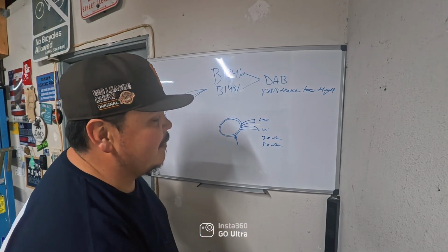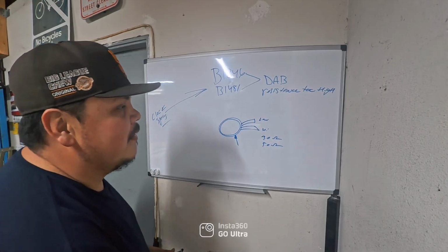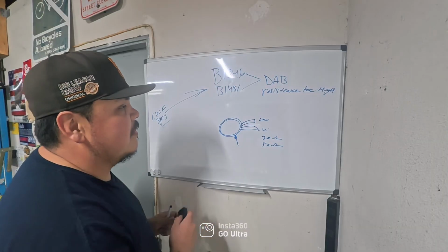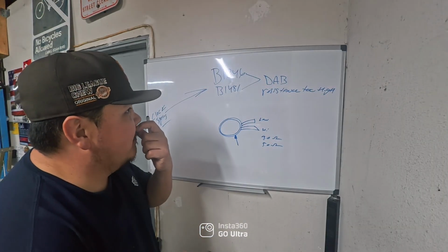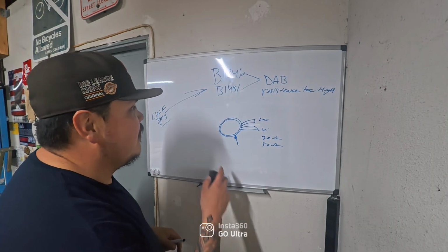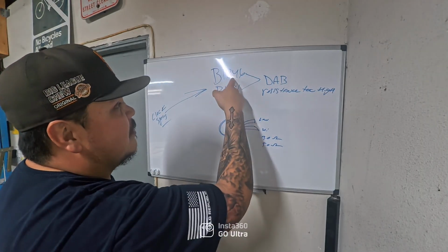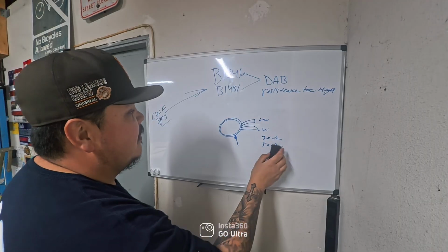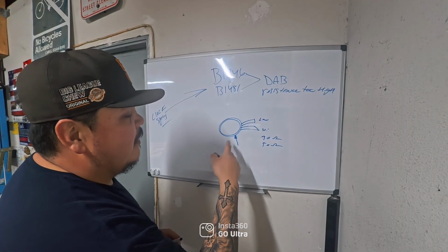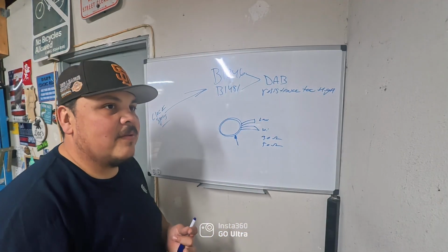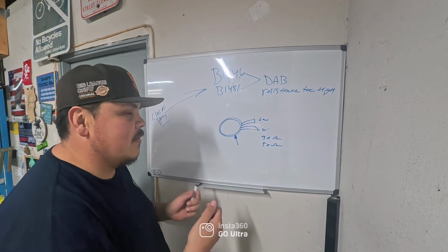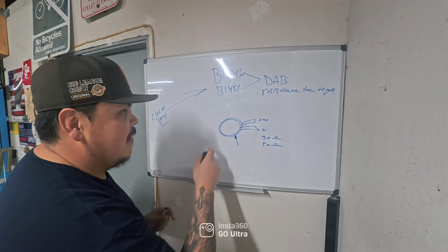I don't think I've ever replaced a driver airbag in my career, and it's been 15 years. It's always the clock spring. And like I said, most of the Hyundais do have an extension on it for trouble codes B1346, B1481. And speaking of clock springs, if your horn doesn't work, or your left side or right side steering wheel controls don't work, I'd be looking at the clock spring as well.